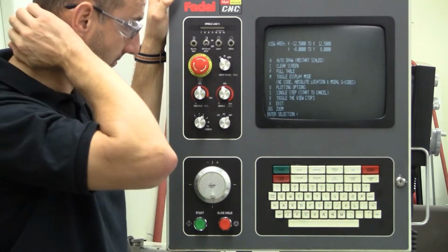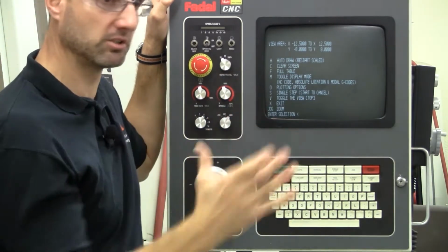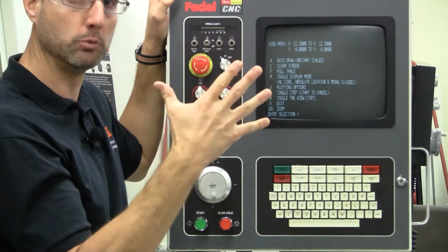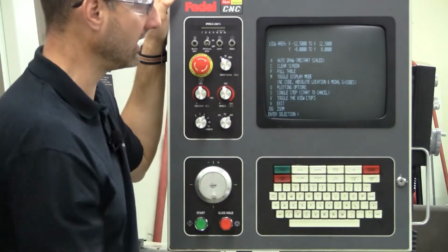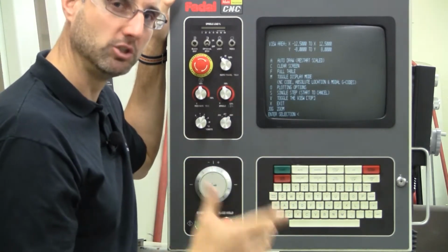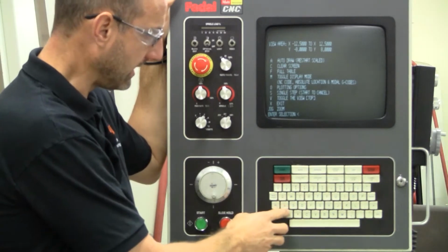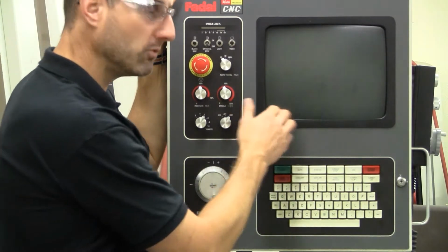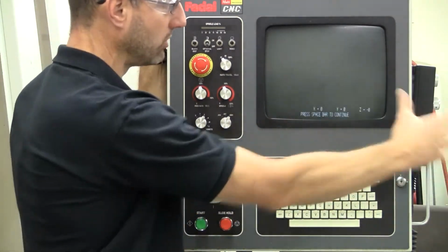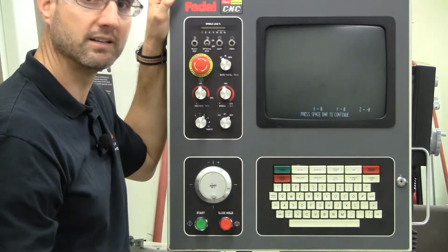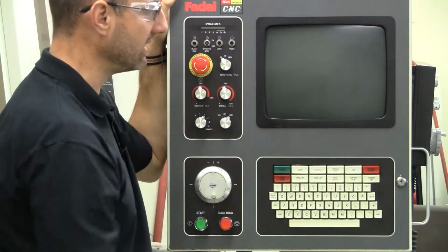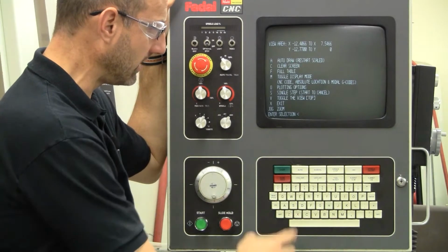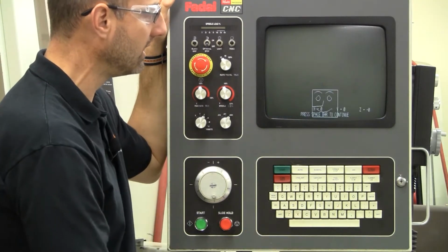Auto Draw is supposed to rescale or rezoom your program so that it shows up correctly on the screen, but it doesn't always do it. So typically we'll hit A for auto draw, and it'll run through, and it actually ran the program, but it ran it somewhere off over here. And so if auto draw doesn't reset your program so you can see it, then just hit the space bar and go back and press C for clear screen, and there you go.